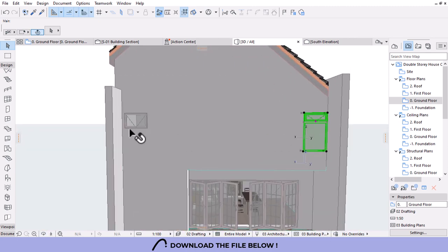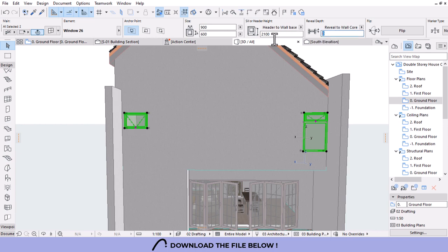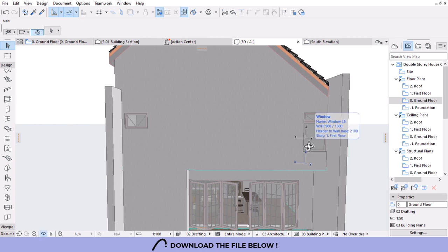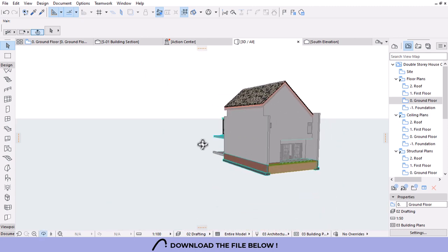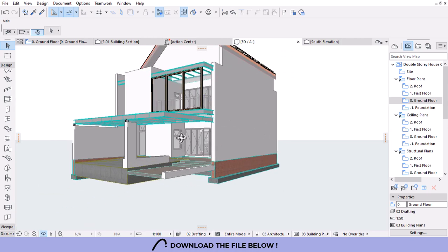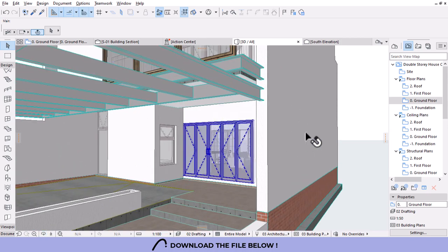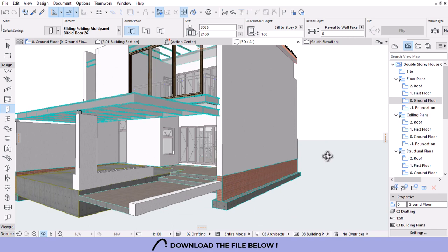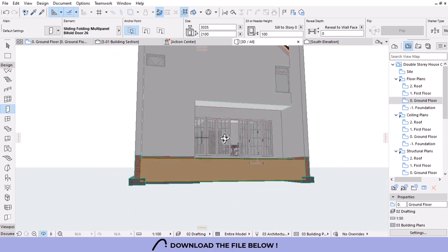And then let's set the windows reveal to 90 like the others. Yeah, I think this has to be the same with that. So I'll pick parameters of this and then inject to here.